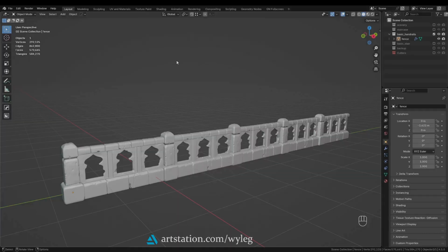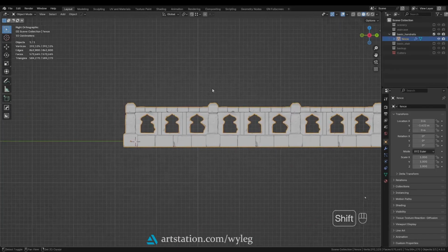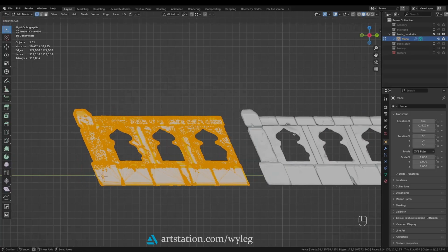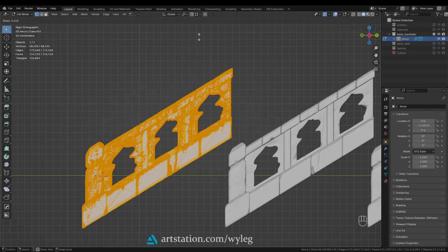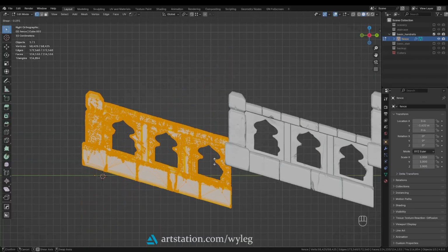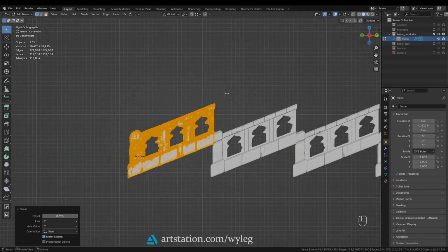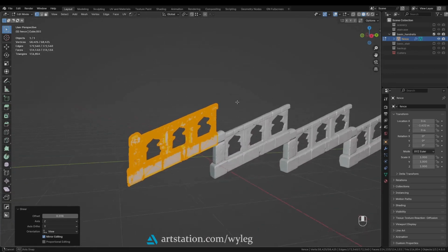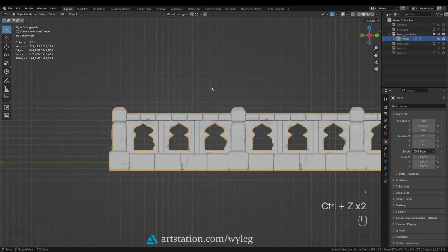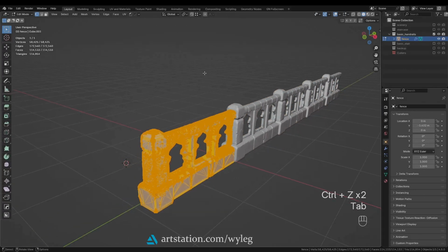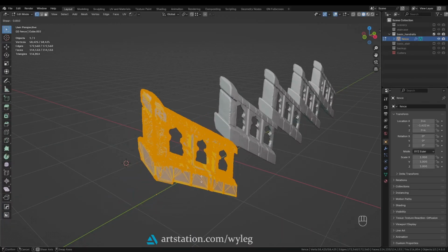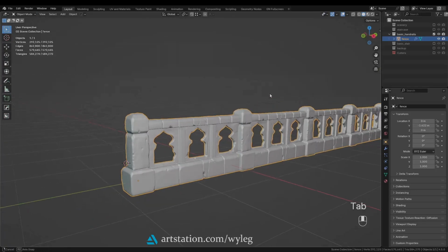Step 2. We need to skew the mesh. In Blender there is a tool that can give you the result we want. It's called a shear tool. It works something like this. This tool has two downsides. First, it's really awkward to use, especially since we want to shear it on the vertical axis, and also because it is dependent on the camera angle. And second, it is a destructive tool, meaning we won't be able to adjust the effect later if need be. So we won't use that.